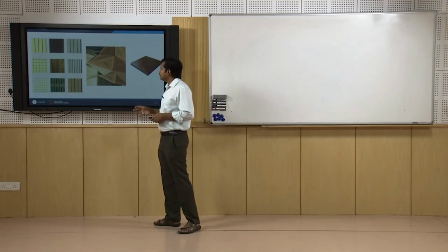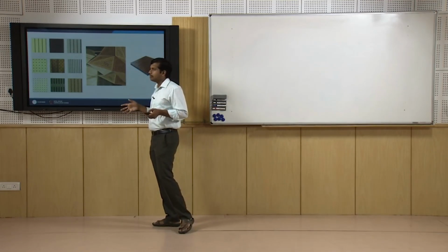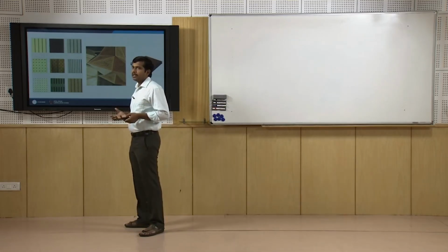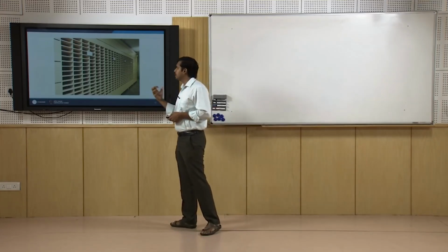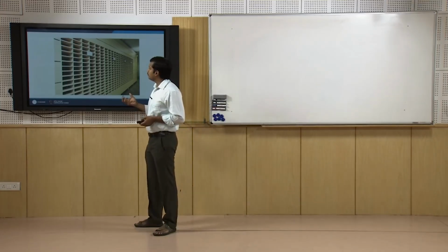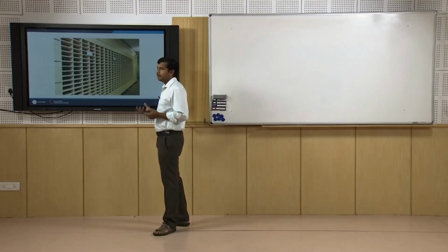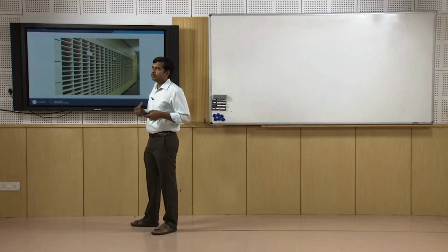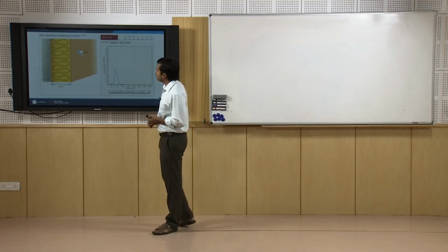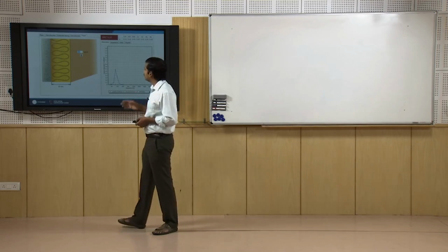Apart from this, they can also be separately suspended in the form of specific boxes which act as resonating cavities, or like I said, it can be individual cavities which can arrest very low frequency sounds, typically used in recording studios where low frequency creates a lot of problems because of the smaller volume of the room as well as the type of sound signals which are generated. A few examples, first let us start with cavity, panel resonators, panel absorbers.